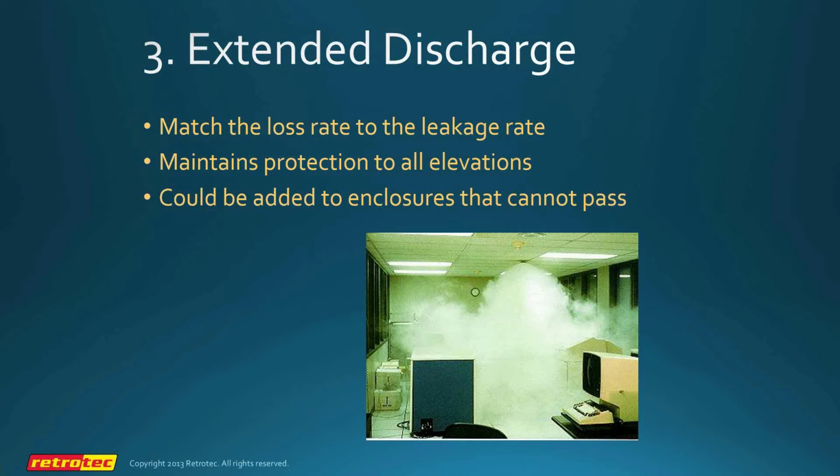All that we do here with extended discharge is to calculate the loss rate, and as long as we keep continuously discharging at the loss rate, we can have a retention time for as long as we want, forever, 30 minutes, 2 hours, whatever. This is often added to enclosures that have large intentional openings, and so we keep discharging at the rate of loss to those openings, and that is something that needs to be considered.